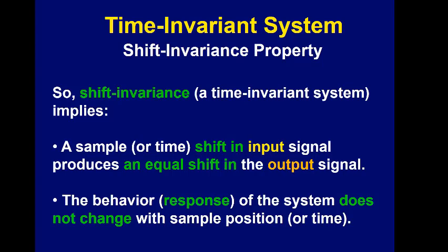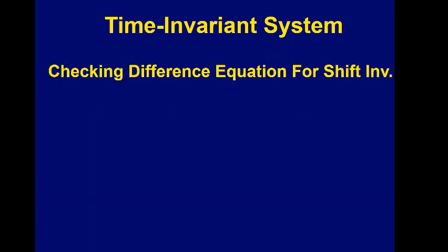Now, over the ranges of times that we care about, they act like they are, and so that's not necessarily a problem. The beautiful thing about discrete time systems is that most of them are based on just computations, and those computations aren't going to change over time unless somebody dabbles with the coefficients or the equations themselves. So it's easier in some ways to make a shift invariant discrete time system than a continuous time system.